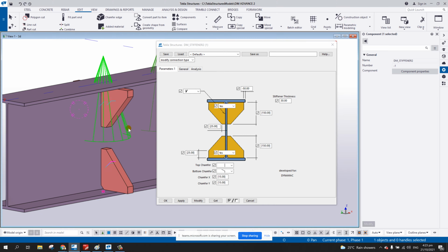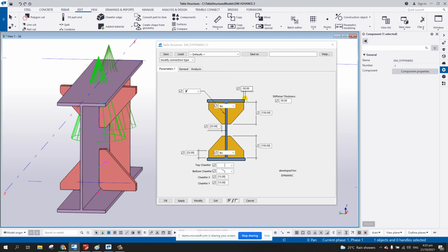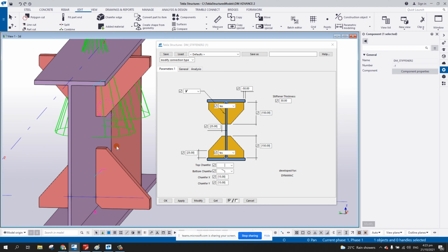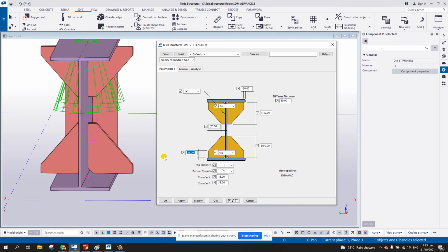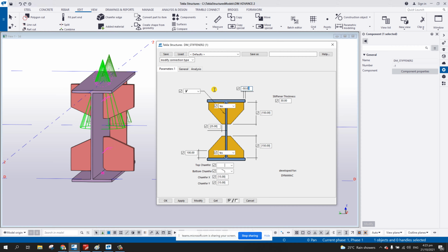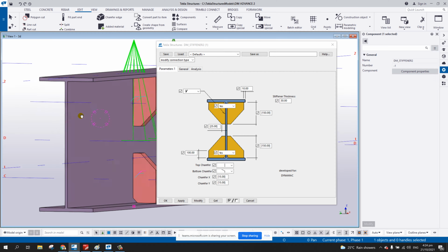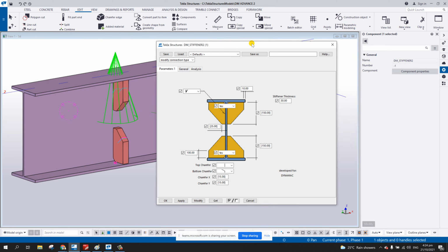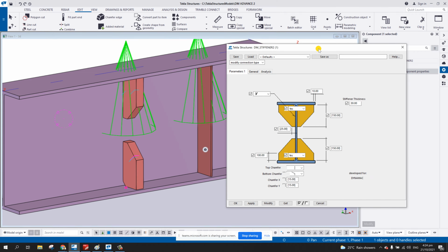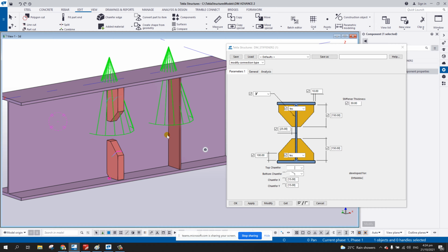But again, if you notice here, I control it only one time. So meaning if you want to control each and every wing plate, then you need to add the parameter. Okay, like what I've said. So here, if you want to have here 100, modify, and there you go. And here 10. So you have now the desired stiffener with a picture. It's like an hourglass, right? Okay, so do that one.